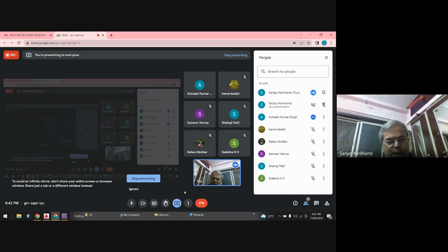You may find this very common in the Middle East, and that's why Sulekha madam asked me, sir, that here the slab-beam concept does not work, and definitely does not work. Most of the projects right now in progress in the Middle East are commercial structures where flat slabs are there, column capitals are there. Sometimes they have drop-panel-less flat slabs, and many times they have post-tensioning.